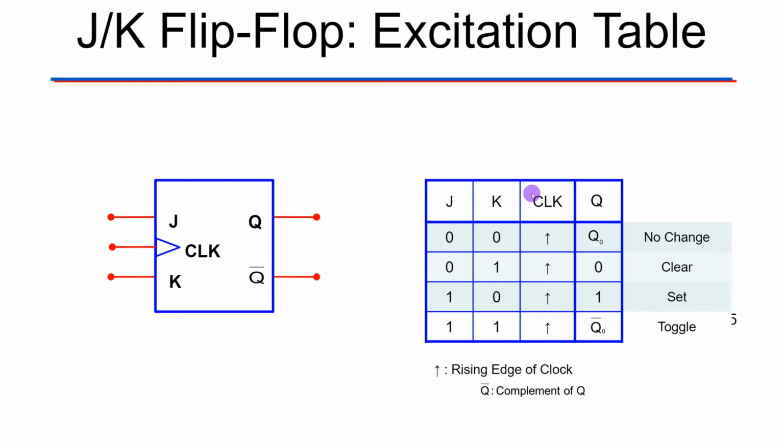And again, this is all rising edge, but the asynchronous comes from these two possibilities right here, which will be built into our other flip-flops. But clear and preset are this idea that we are overriding whatever information was stored, so we don't care what was stored here. We are, for whatever reason, clearing out this information to 0, which is what we'll actually be doing in our counters, to simulate having a range.